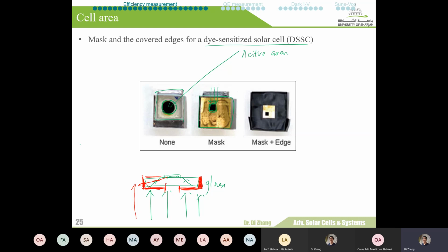because you cannot fabricate the solar cell without the glass. The glass has to always be there. So any losses in the glass are not a measurement error. They are losses that you naturally have in a thin film solar cell. With a thin film solar cell, you always have to use a transparent substrate. If you want to improve your performance, yes, we could try to go for a more transparent glass and reduce the absorption in the glass, but typically we do not consider this a measurement error, because if you deliver your solar cell, we consider it a black box.